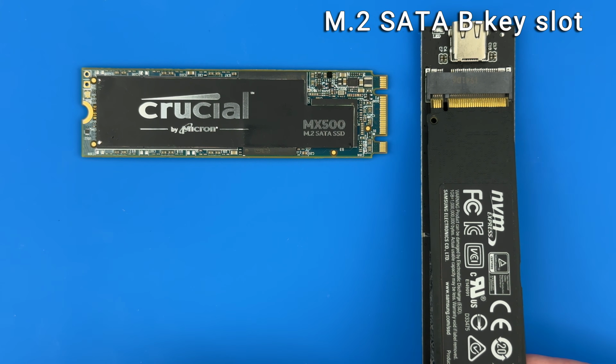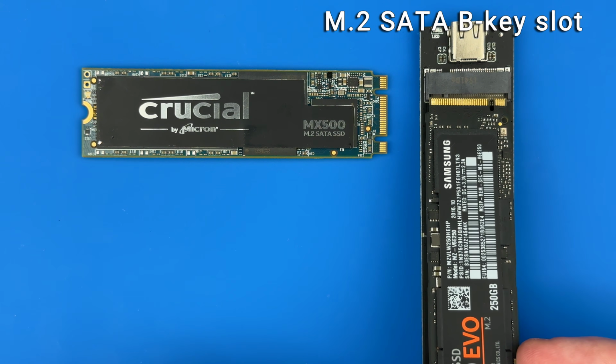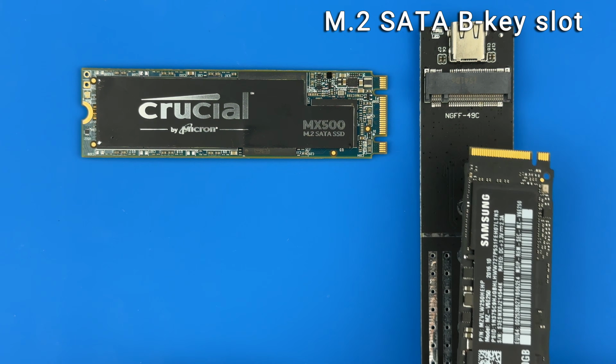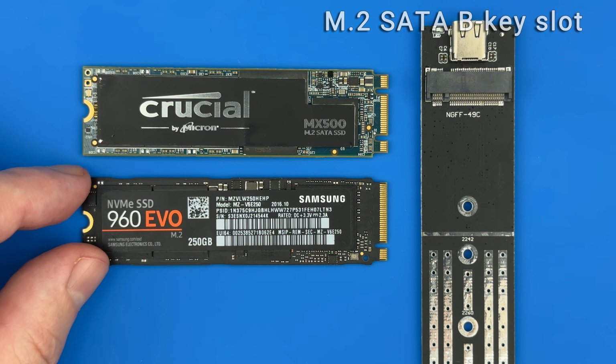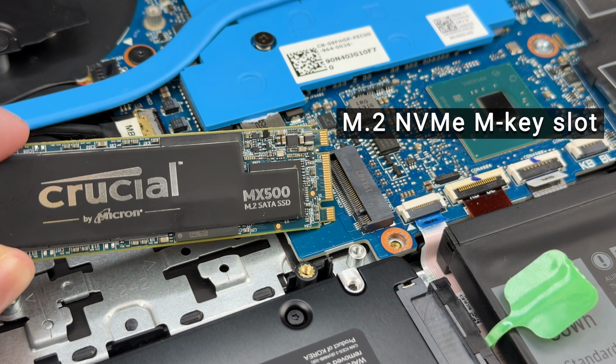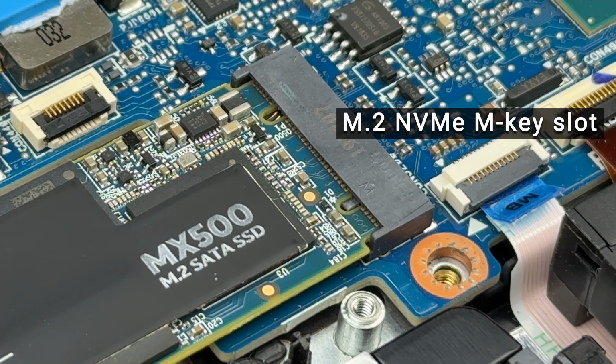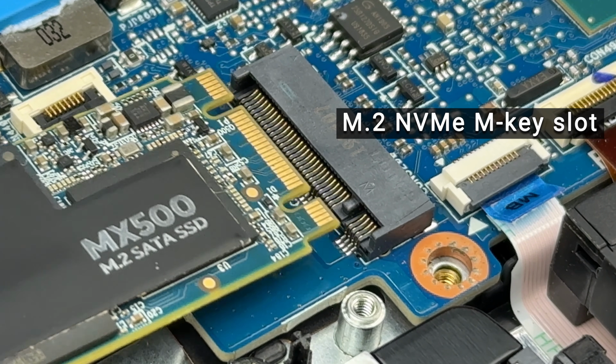This means that you cannot install an M.2 NVMe SSD in a device that does not support the PCI Express interface. Therefore, it is important to check your device's specifications, particularly the type of slot available on your motherboard, before making a purchase. A common question is whether an M.2 SATA SSD can be installed in any compatible slot and work with any device. The answer depends on the specific device.